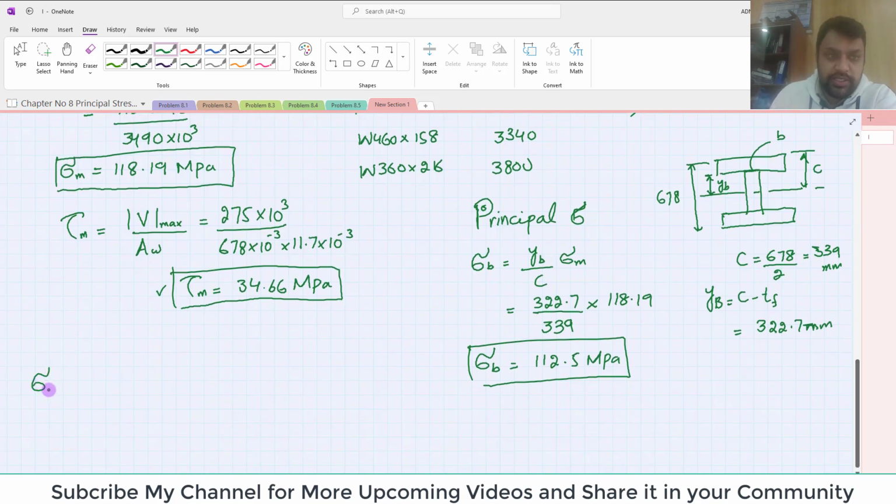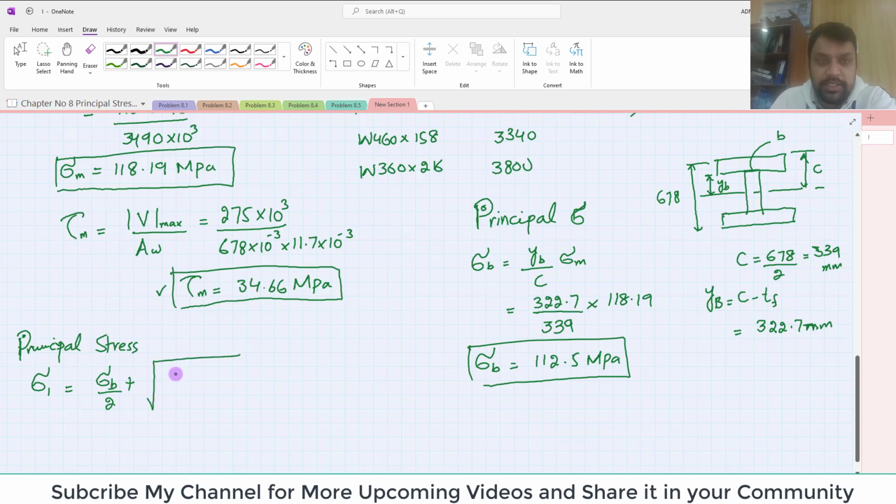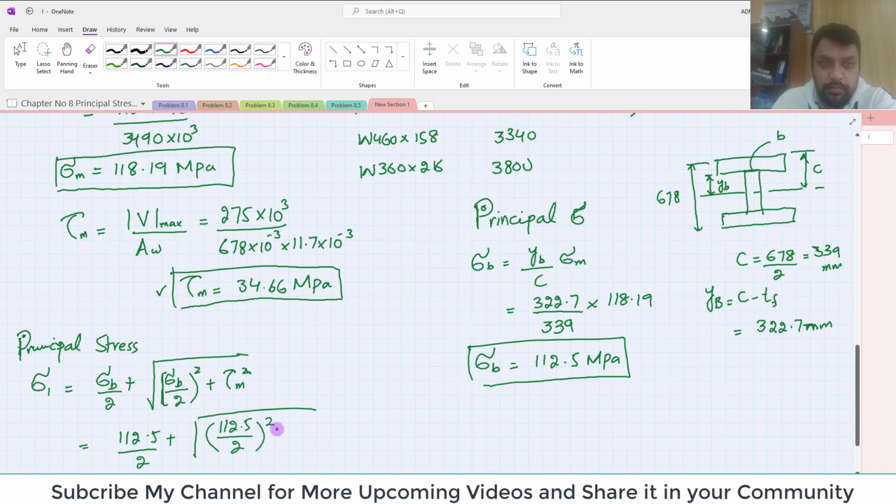Now for principal stresses we can use this shear stress as well. Principal stress sigma 1 will be equal to sigma x plus sigma y divided by 2 plus the root of sigma x minus sigma y divided by 2 whole square plus tau maximum square. We have only sigma b, so sigma x is sigma b, and sigma y is equal to 0. So you can put the value: sigma b is 112.5 divided by 2 plus the root of 112.5 divided by 2 whole square plus 34.66 whole square. When you calculate it, this will give you 66.08 megapascal.